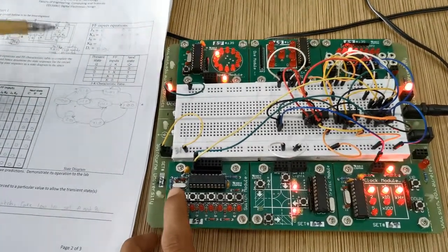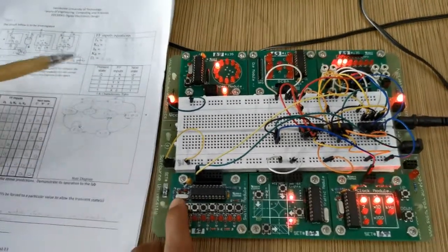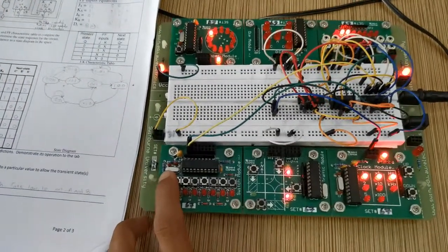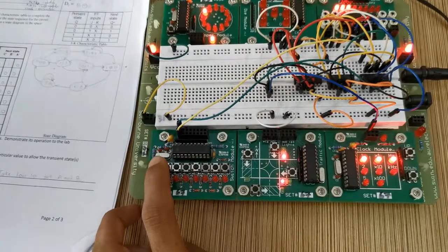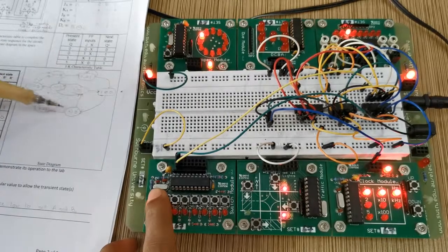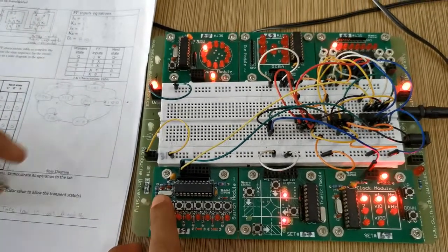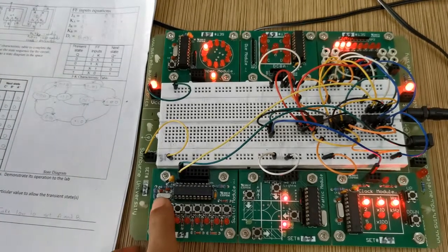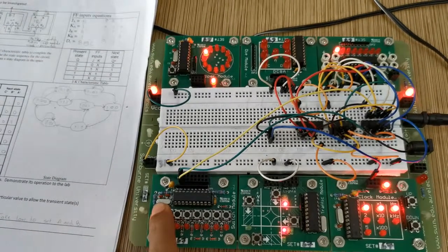There's another two things I'd like to mention. Once we enter the inner loop again, rotating between 111 and 011, the point at which we enter the outer loop will be reflected within the state diagram as well. So if you were to leave at 011, then we will begin with 100 and then enter 110, 001, 000, and so on. And if we were to exit this loop at 111, then we will start with 000, 010, 101, and so on.